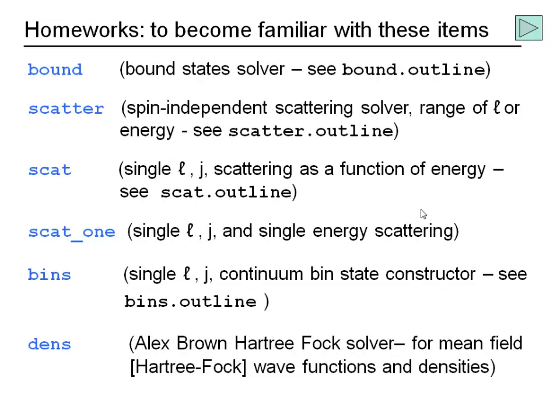So what I'm interested in day one is that when you dial up that particular option in the code that you want bound state, number of nodes, clusters, how many, when you're dialing up these various inputs, you should know what the consequences of putting a 2 or a 3 in a certain position are. Because it's very easy to get a data set that seems to work, produces something that looks vaguely sensible, and then just twiddle the numbers. But unless you understand what the inputs are, it's a death trap.